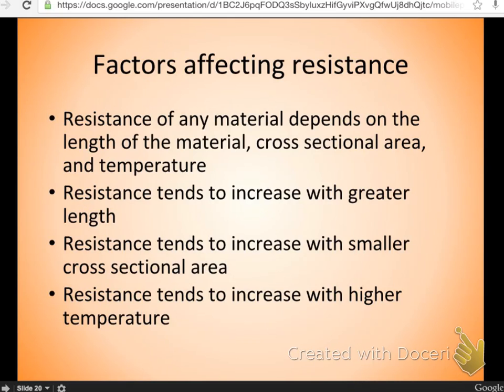It would keep running, but it was an electrical relay that when it got hot, basically it wasn't functioning the way it was supposed to, and some of the other things that would have mitigated this effect weren't working. When that relay got hot, the resistance climbed to a point where it would no longer conduct current and the vehicle wouldn't start. So if you forgot and shut it off, you had to go cool your heels someplace for 20 minutes before you could turn the truck back on. It was a lot of fun.